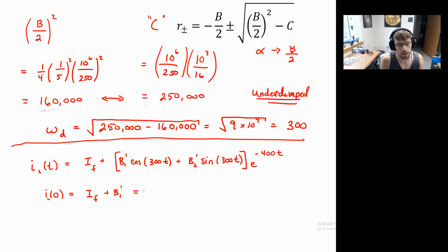This should just be 10. What we have to think about for a moment is what is the current at a long time, at time equals infinity, after the switch is thrown. And for that, we can think, oh, wait a minute. We have a potential source, a 10 ohm resistor, and then after that, a 10 ohm resistor, a capacitor, and the inductor.